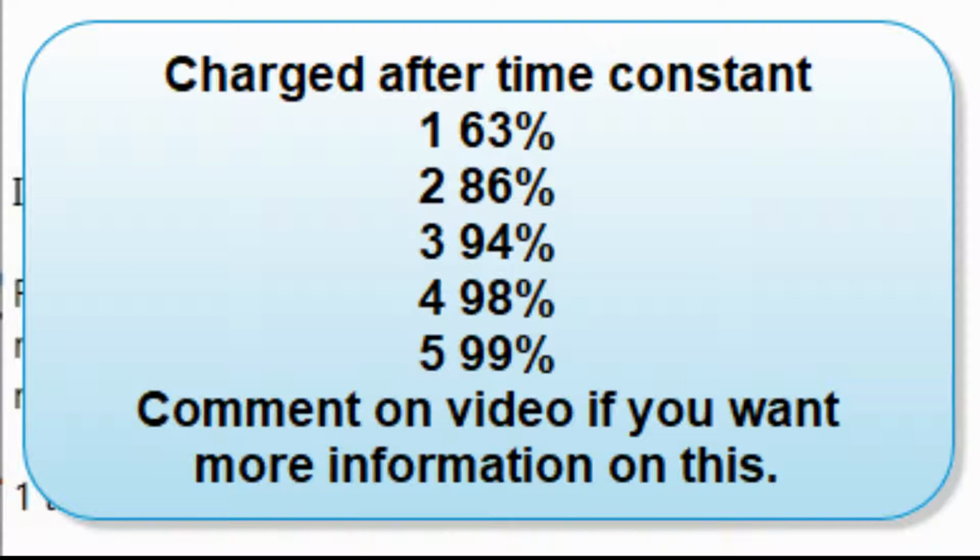So the first time constant gets us 63% of the way. After the second time constant, we're 86% of the way. After the third time constant, we're 94% of the way. After the fourth time constant, we're 98% of the way. And then after the fifth time constant, we're 99% of the way. That's why they say it takes 5 time constants to completely charge the capacitor. It's not fully charged, but it's 99% of the way.